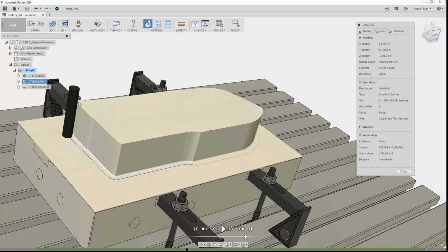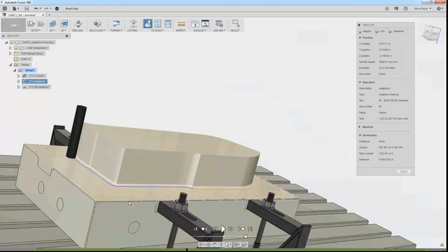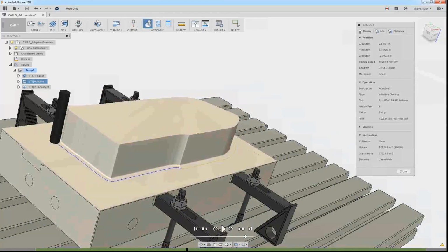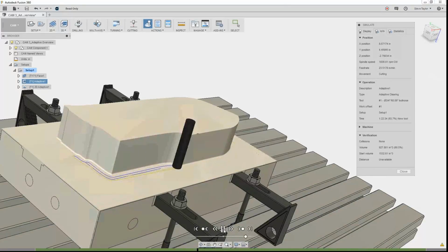So there's a lot more of the flute length left, but as you're looking at it, you can see we're using it to as much as we can, the depth. If we zoom in, you can see a black line. So if we actually look here, that black line there, that is actually our finished model size. So you can see we're actually leaving some clearance there from it. And what we'll also see down at the bottom here is this green line. Now, if there is collisions or there is a problem, you'll notice later on there may be some red parts, which might be to do with the length of the tool that we're using. So I'll just let that go.